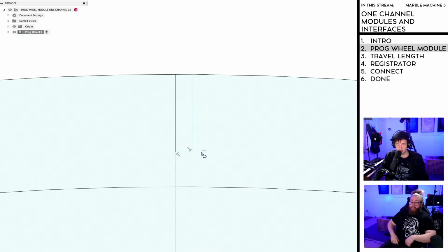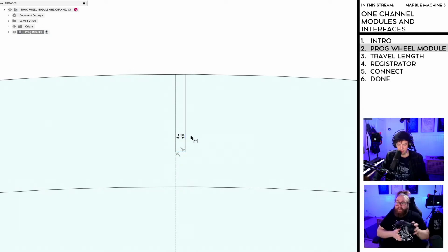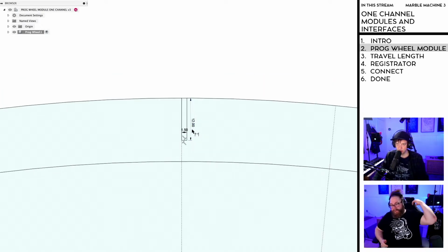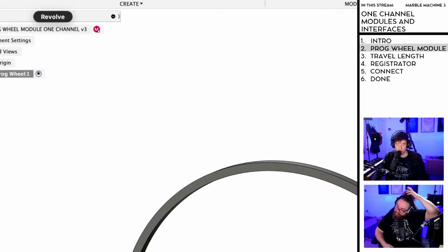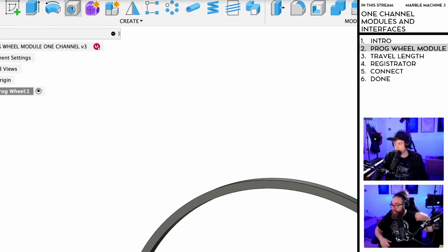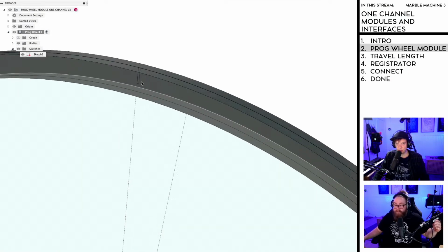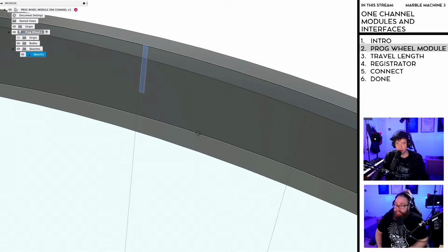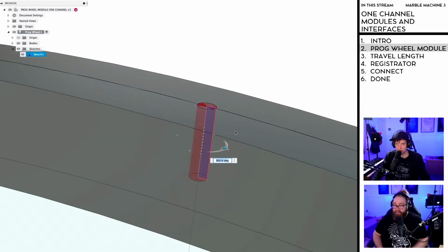I can then say this is now the radius of the programming pin. So we're going to use 3, so I put 1.5, and then I can put the length from the top. Let's go with 12. And now when we go out into our body, we choose a revolve. I'm repeating myself, some of you have heard this spiel so many times, but it's really, really useful, I think. Then I just choose this profile and I choose the middle line.